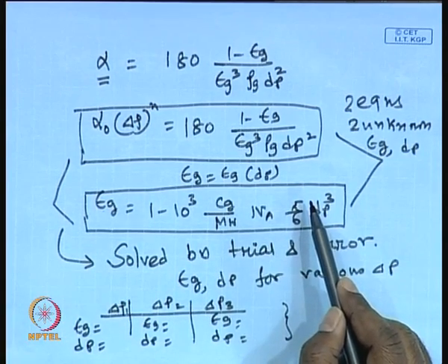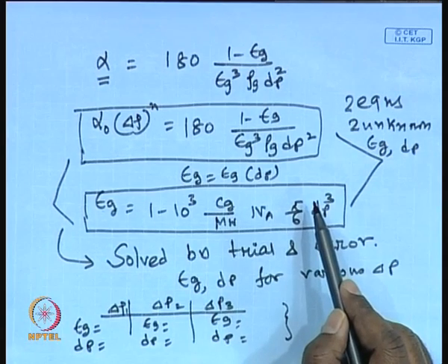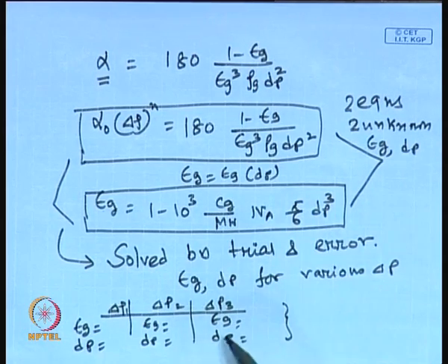So, everything will be fixed, but in most of the membrane filtration process, we are not talking about the hard sphere, we are talking about the polymers, we are talking about the polysaccharides, we are talking about the gel not forming of solids, but by the high viscous liquids. Okay. In that case, the equivalent particle diameter and equivalent porosity at that particular operating pressure can be estimated by this method.